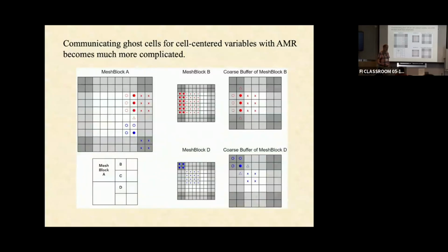So everything is done explicitly, and at every time step, in fact every sub-step, if you're doing an RK2, RK3, RK4 time integrator having 2, 3, 4 steps, you have to communicate your boundary conditions to make sure that the sub-steps have boundary values which are in sync. So all this boundary communication is happening at every sub-stage of your time integrator, whether it be RK4, whatever it is.